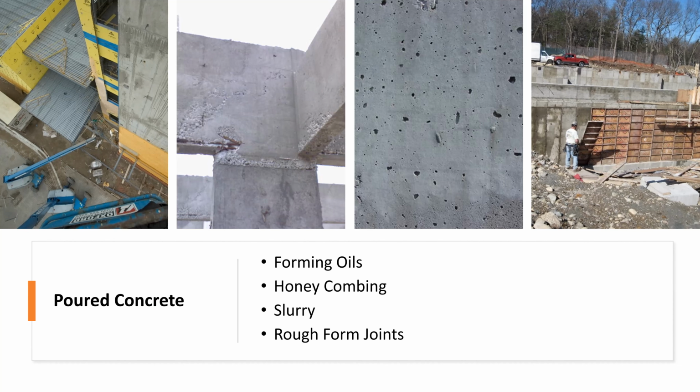When it comes to the honeycombing, the second picture from the left, you can see again, you have some exposed aggregate. If you're using a self-adhered membrane, maybe you can go over top of it if it's not too bad. If you're using a fluid, you may have to do some grinding, some parging, something to make it a little bit more smooth.